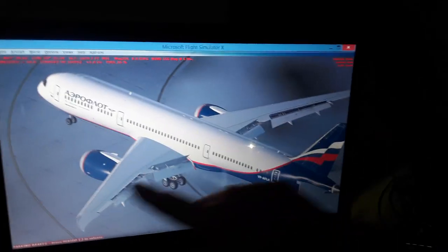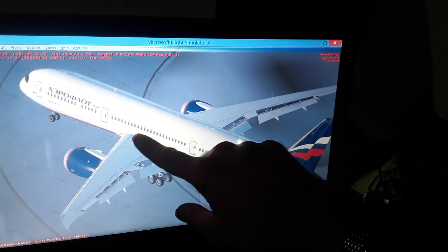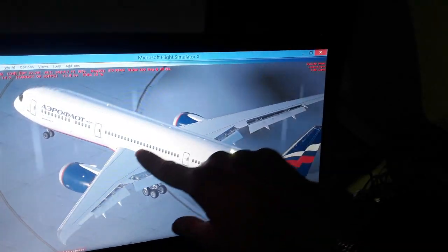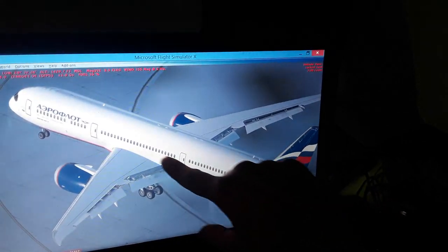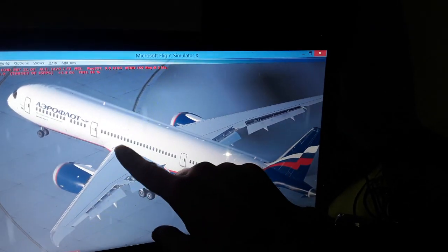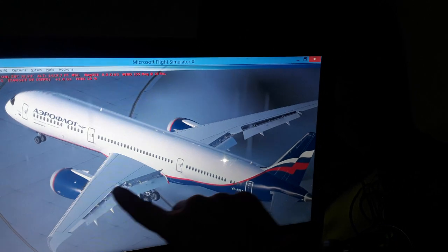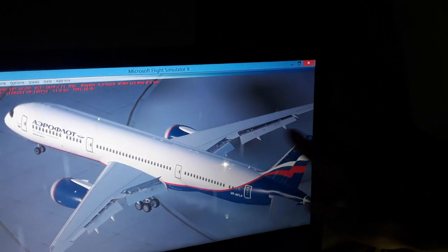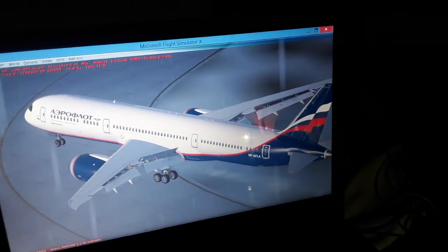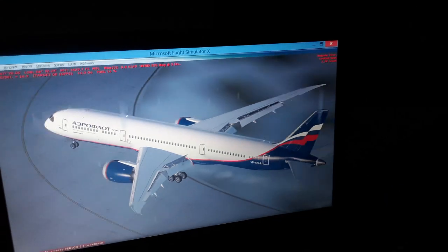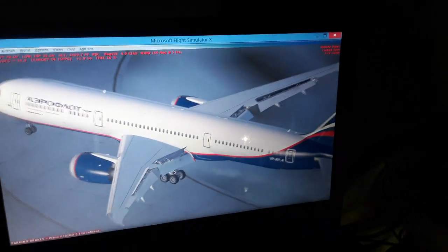You can see we have the mean aerodynamic chord position, the MAC. About 23% of the mean aerodynamic chord is where the maximum dynamic lift occurs in the wings. The center of pressure also can shift backwards when we fly, and also the stall begins when we fly. Over here the airflow becomes detached all the way back from the top surface of the wings, and we have the stall of the aircraft, so we need to avoid it for a given angle of attack and airspeed that is changing.